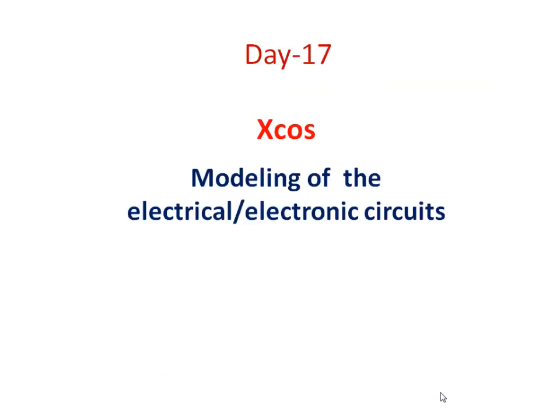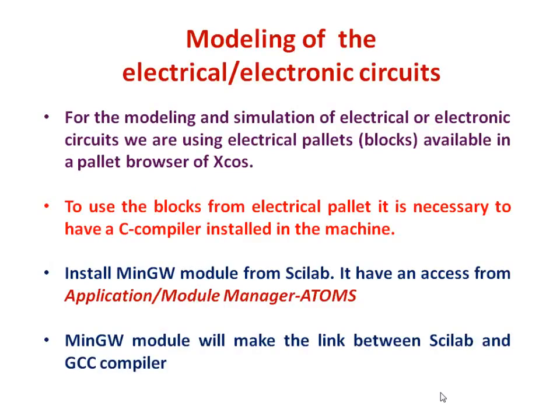Today on this 17th day of this online course, I am going to demonstrate the modeling of the electrical or electronic circuits in Xcos. For the modeling and simulation of electrical or electronic circuits, we are using electrical palettes or blocks available in the palette browser of Xcos. To use these blocks from the electrical palette, it is necessary to have a C compiler installed in the machine.